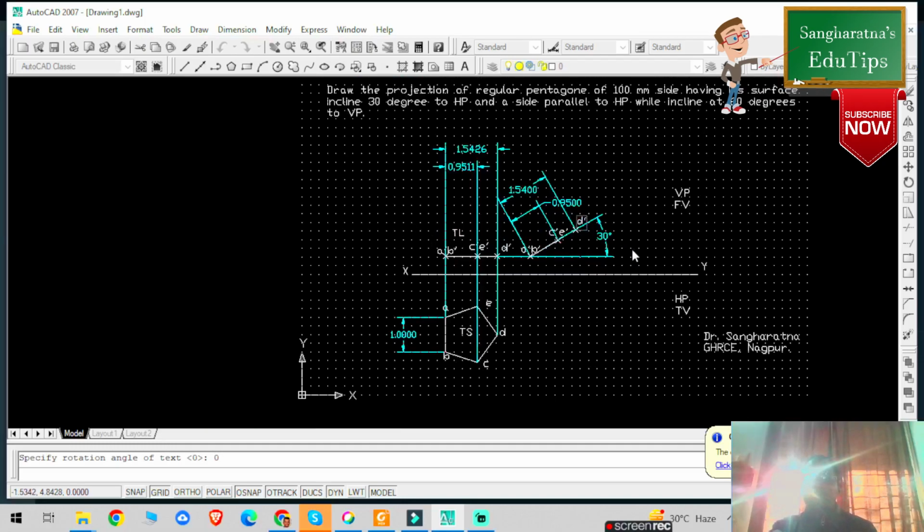From this particular point, dear students, now I need to write down the text. If you know the commands, you can quickly repeat the steps. Here basically it is D dash. Now I'm pressing the escape button. Now I'm drawing the perpendicular projections from this particular point, right? Escape, draw another projection from this particular point, right?